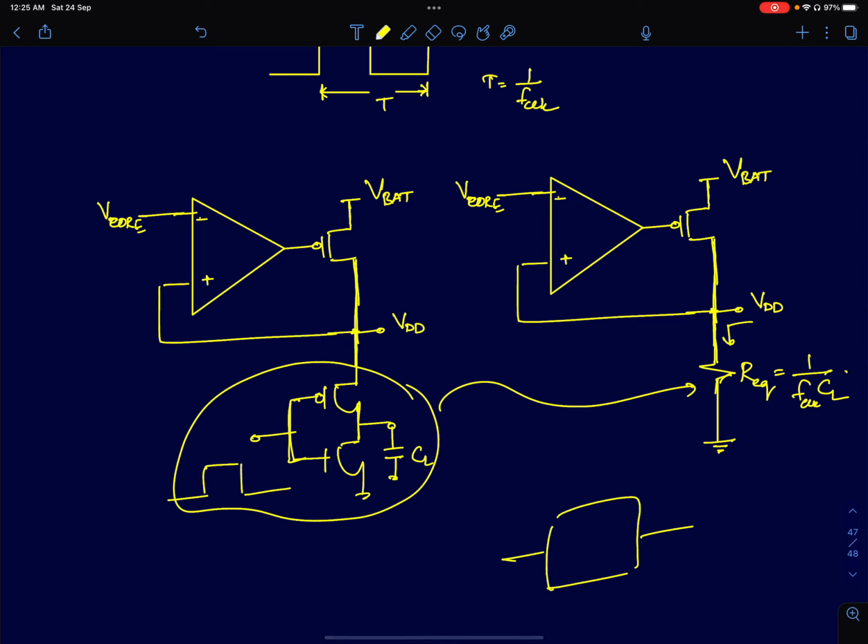If you have a complex digital circuit and you know the power, you can typically reduce it to an average current, which means you can estimate its equivalent resistance. That equivalent resistance is what you will use in your circuit model when you're designing your LDO, and then we can perform all the conventional AC analysis to estimate its stability and all of that.